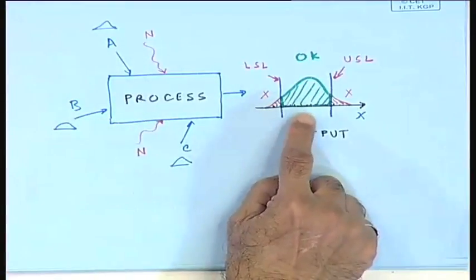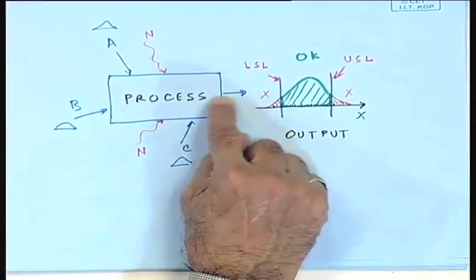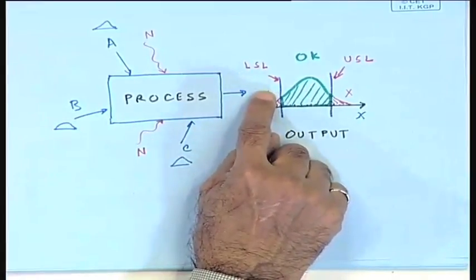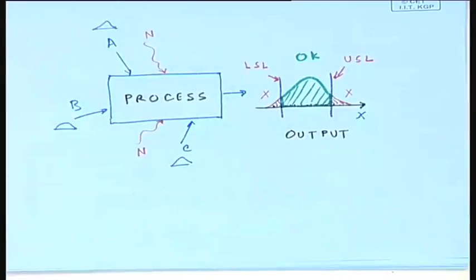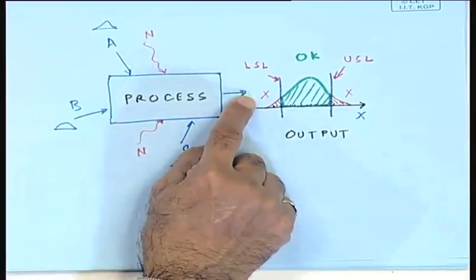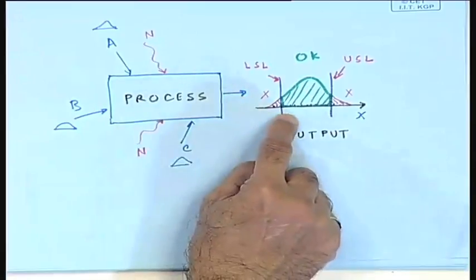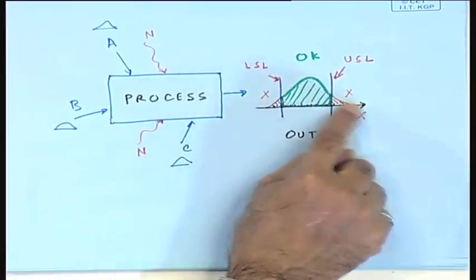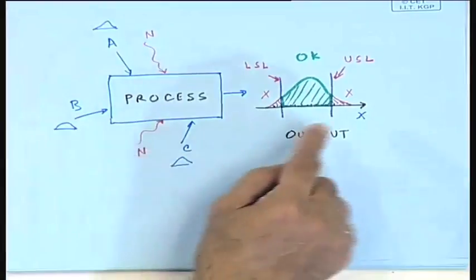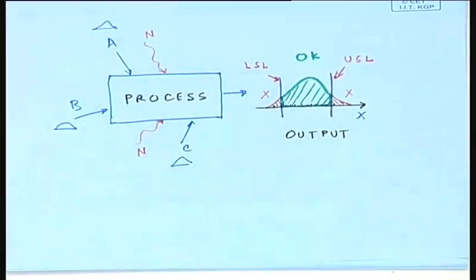You look at the causes of variation. You monitor the process using a control chart. You look at the output. If it turns out that you've got a lot of assignable factors there, then of course you go back and do an investigation there. If you've taken care of the assignable factors, then you look at the spread of the process, because that is now the natural variation of the process. If that goes either above or below what we call the tolerance, you have to then adjust, you have to play with the sigma of the process. And this again, like I said, can be done. This is the overall variability of the process. And one great way to tackle that is to apply design of experiments.